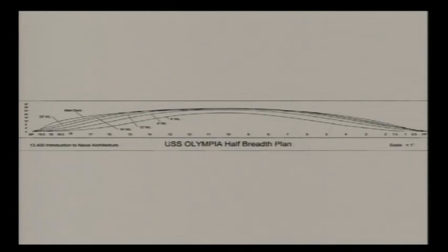These are the water lines in the top view. So, it is very important that you get this idea. This whole thing of lines plan is very important, because it is, so to speak, the crux of your naval architecture. From this you develop the design, from this you develop the marine structural part, the structural design of the ship, like that. Okay. So, from this you start everything.